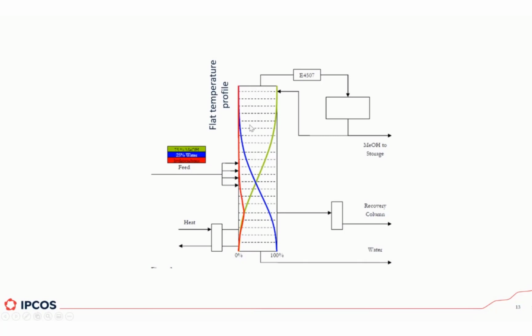The top 35 trays or so were all showing you exactly the same temperature. I mean, with changes in the third decimal figure of your temperature indication, which is most likely within the margin of error of measurement itself.